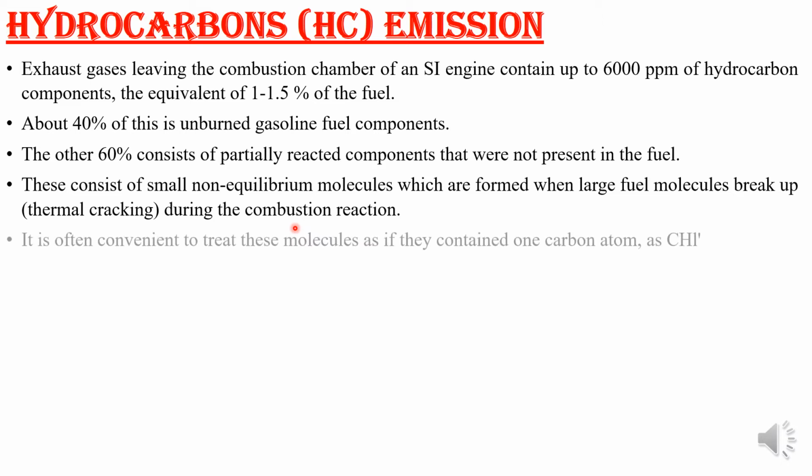That is hazardous to the environment. These unburned hydrocarbon emissions are the direct result of incomplete combustion. The pattern of hydrocarbon emissions is closely related to design and other operating conditions. Two of the important design variables are induction system design and combustion chamber design, while the main operating variables are air fuel ratio, speed, load, and mode of operation. These are the things that form the hydrocarbon emission.